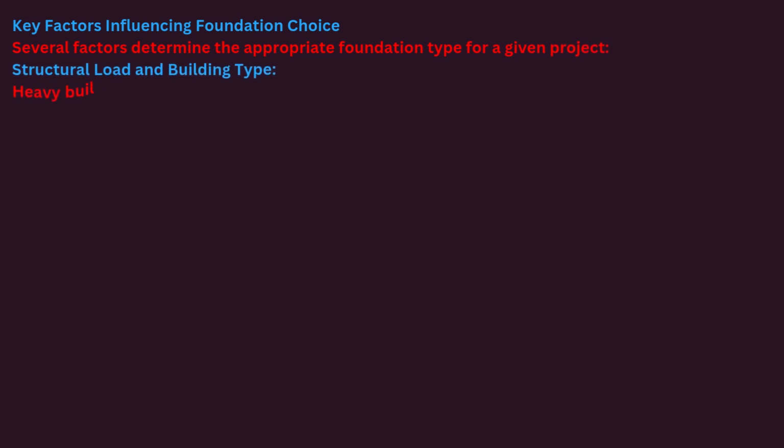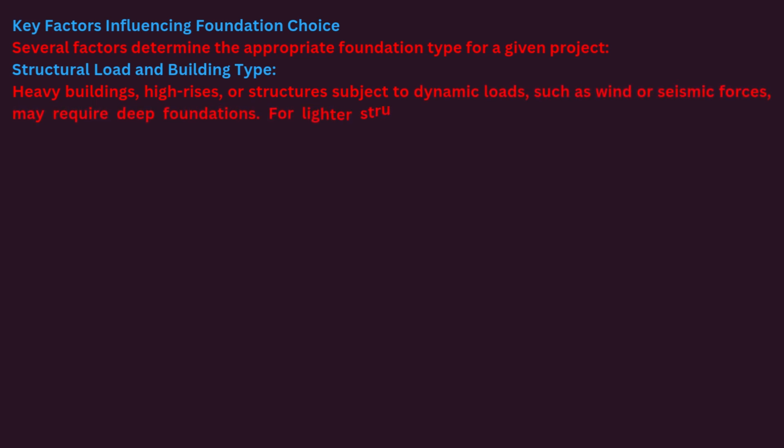Several factors determine the appropriate foundation type for a given project. Structural load and building type. Heavy buildings, high-rises, or structures subject to dynamic loads, such as wind or seismic forces, may require deep foundations. For lighter structures on strong soils, shallow foundations are typically sufficient.